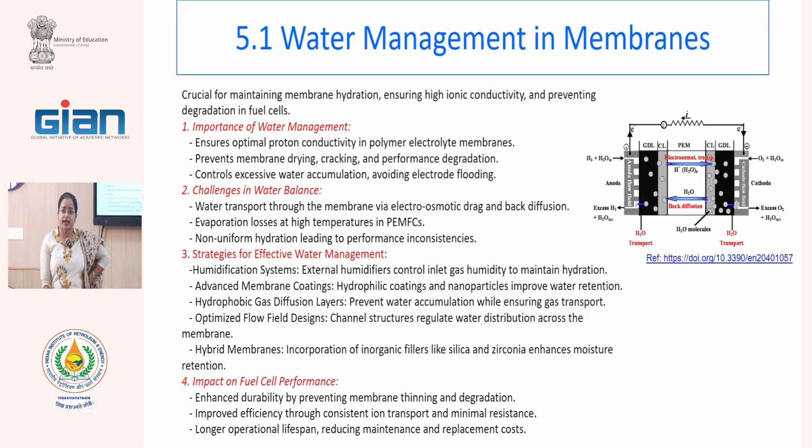Water management is very crucial in any kind of fuel cell, because lack of water inside the membrane causes drying out of the membrane, and drying out leads to cracking and a lack of water molecules to do the vehicular transport. While flooding, too much water, will reduce the driving force for diffusion through the membrane.